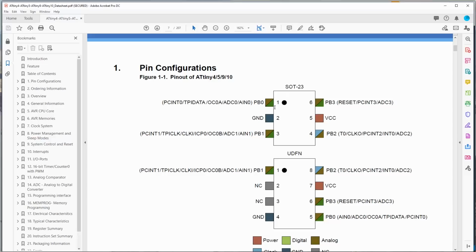All right, so here's our ATTINY6, and if you remember, we need a couple of these for programming. Anyway, let's use PB1 as our sync output. So we only have 4 bits, 0, 1, 2, 3, and then using the high voltage programmer, we can also use the reset line as IO, which we'll need to. So PB1 would be the second bit over.